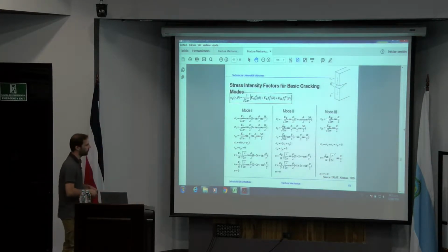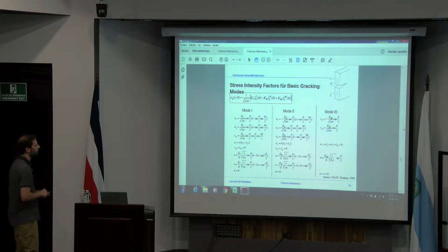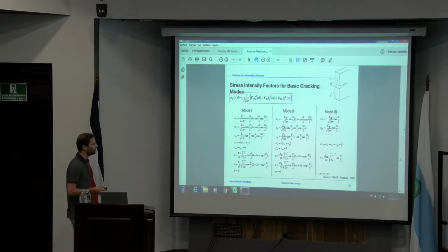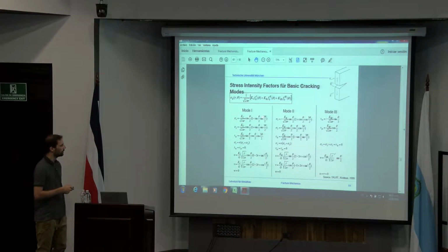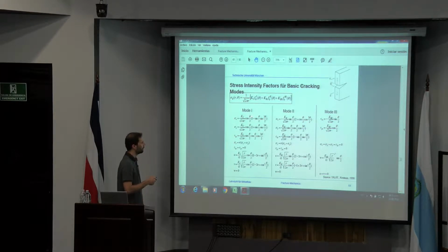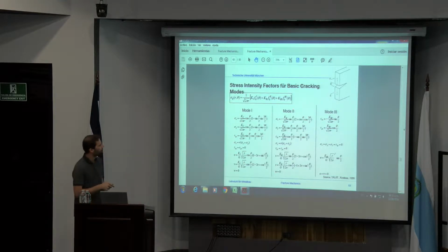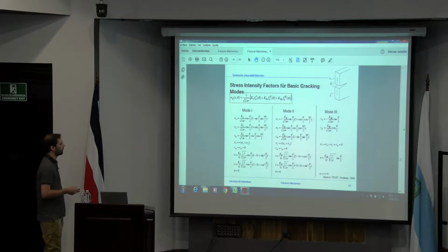These are our basic assumptions, which are derived using a coordinate system at the crack tip. And due to this, we also used a cylindrical coordinate system. As you can see here, you're calculating with r and theta. So the coordinate system is always using the information of the cylindrical coordinate system around the crack tip.